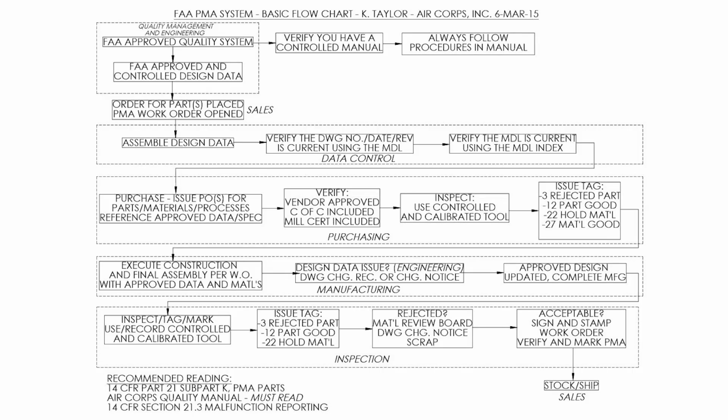That's the block there, lower left hand: execute inspection, pardon me, with your calibrated tools. After that inspection's done, one of three things is going to happen. Again, you could issue a -3 rejected part. We inspected the assembly. This thing's wrong. It's not reworkable. It's red tagged, goes in the red tag parts area.